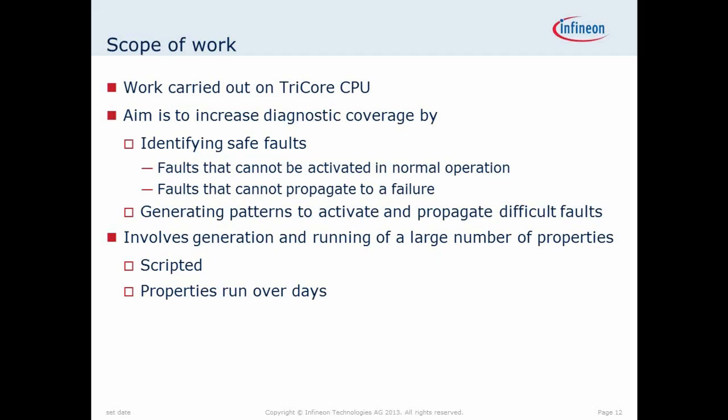So the aim of the work is to increase the diagnostic coverage, to give an accurate measure of diagnostic coverage, let's say, by formal identification of safe faults, and also by formal generation of patterns to activate and propagate some difficult faults. So these are safe faults embedded down in some safety critical logic.